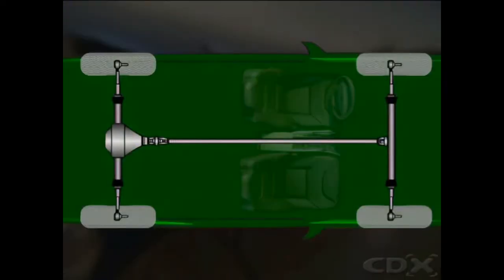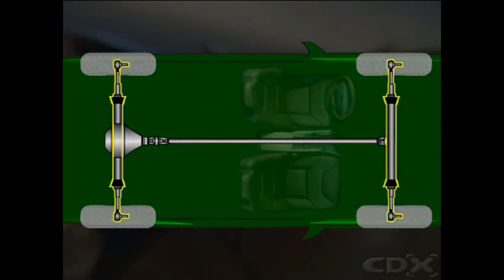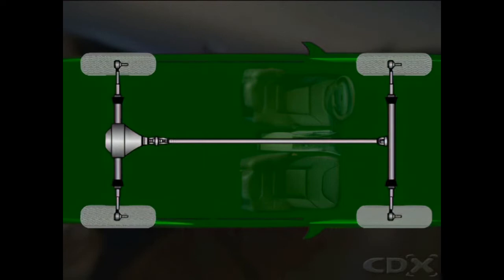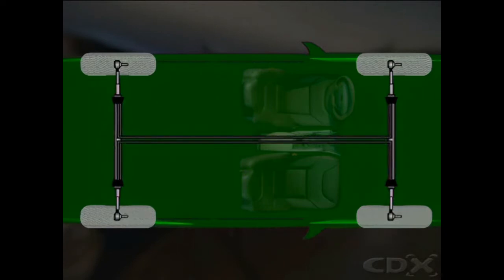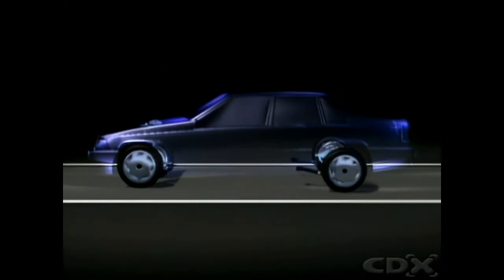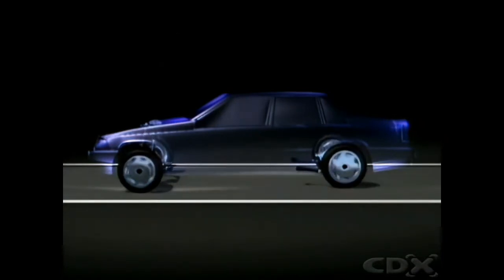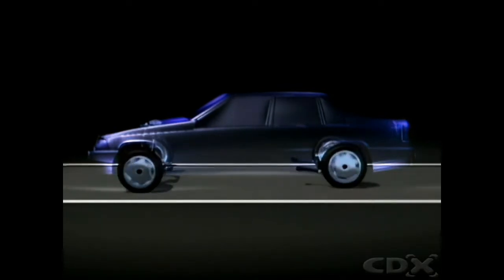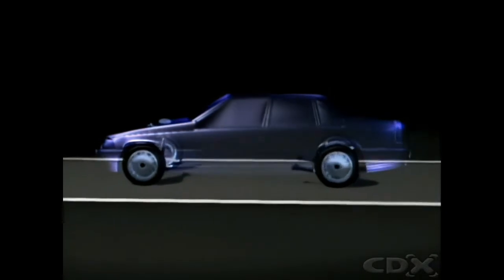In mechanical systems, there is a direct link between the front and rear steering racks through a center steering shaft that allows the rear wheels to be steered within prescribed limits. In hydraulic and electric assisted systems, the center shaft is replaced either by hydraulic lines or by electrical connections that are controlled by control valves or computer-monitored sensors. The relationships between the steering system, the wheel positions, and the suspension system form what is called the steering geometry. These relationships must always stay within manufacturer specifications.